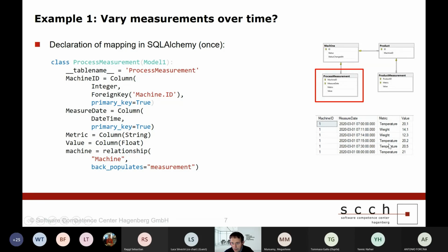You can see here different values measured over time, and one assumption of the process engineer may be that the measurements taken over time must slightly vary. Otherwise, if always the same value is stored in the database, this seems to be an indication that the sensor does not work correctly or something else goes wrong.